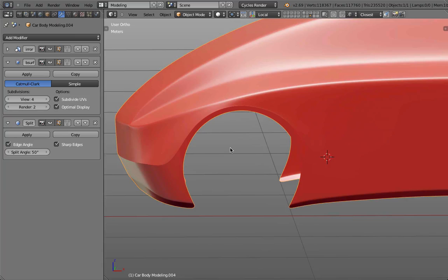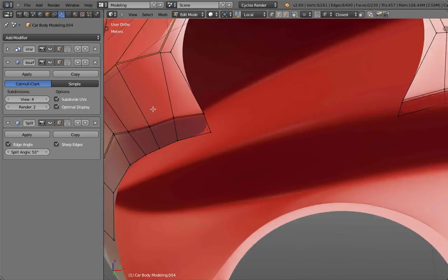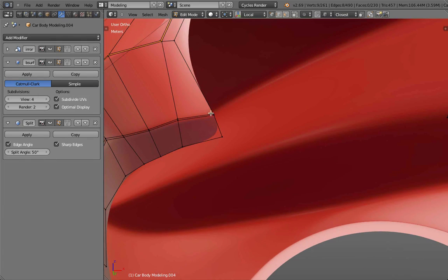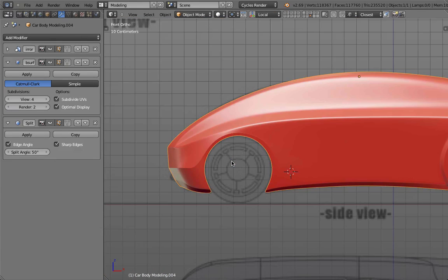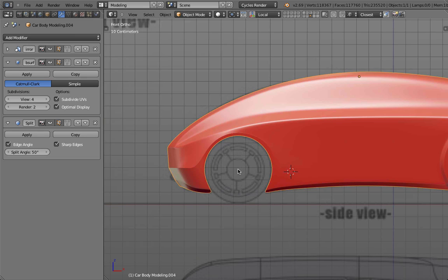But the problem is, without using the edge creasing, you also end up with problems like here, where you can see that the surface is round. Well, I could go into Fusion, import this mesh, turn it into T-spline, then with T-spline crease this edge and then export it or convert it to B-Rep. But since we're in Blender here, we can just prepare all the geometry, so I don't even have to do these tasks in Fusion, because in this process it would be a little bit unnecessary.